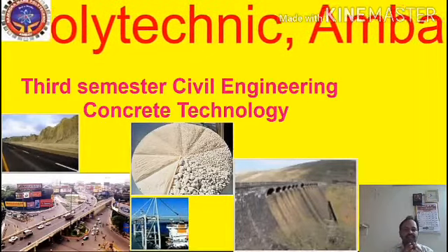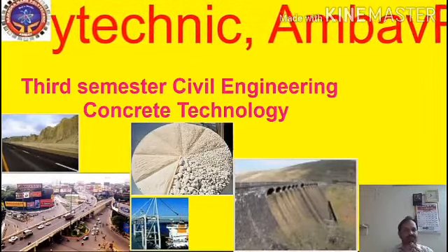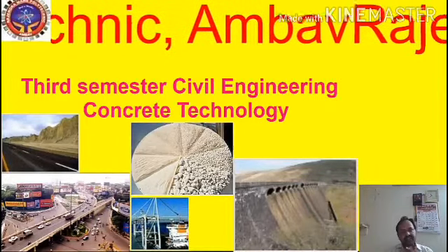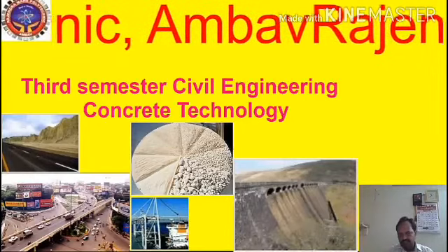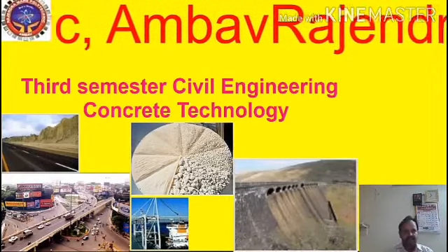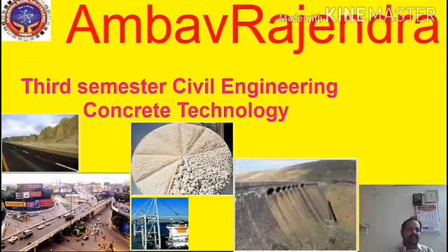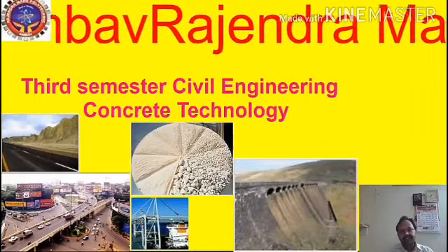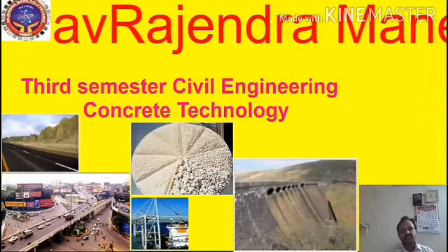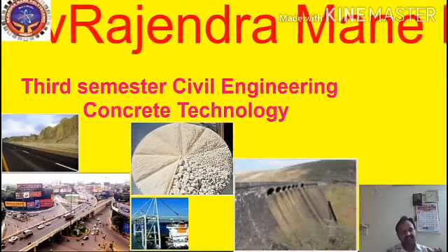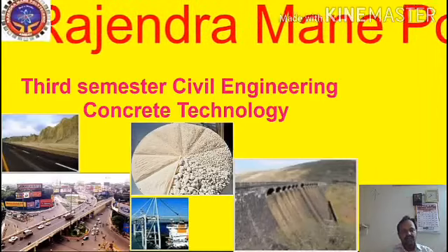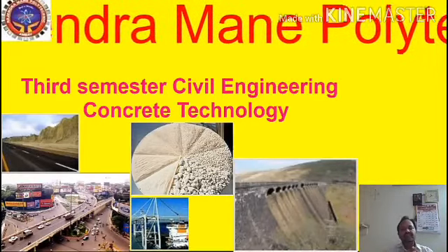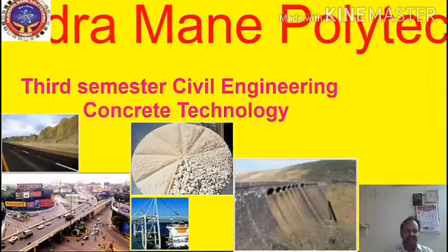The constituents and the fineness of cement are maintained in such a way that the concrete remains in plastic condition for a certain minimum time. Once the concrete is placed in the final position, compacted and finished, it should lose its plasticity in the earliest possible time so that it is least vulnerable to damage from external destructive agencies.